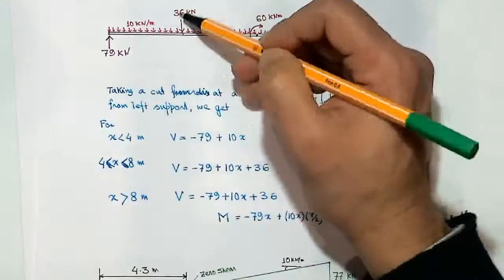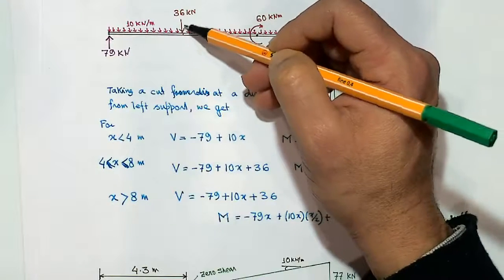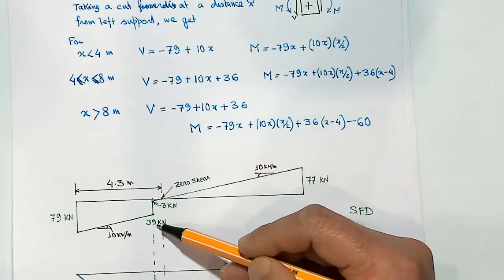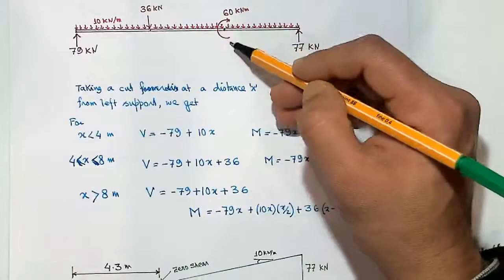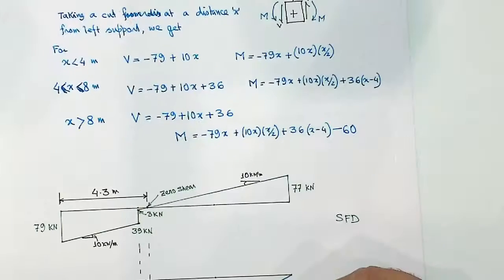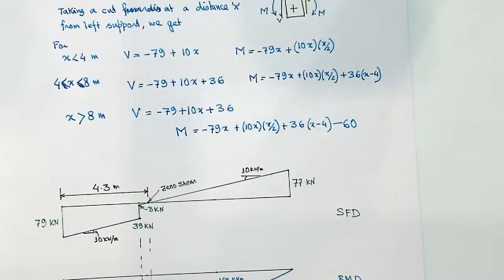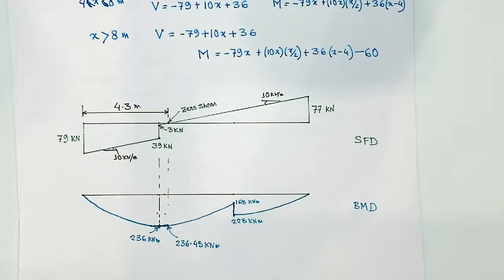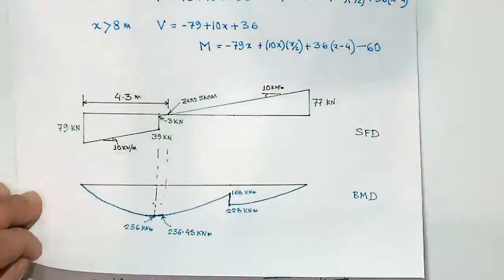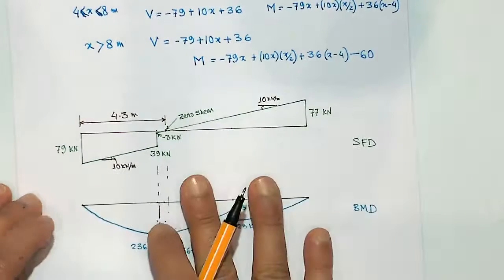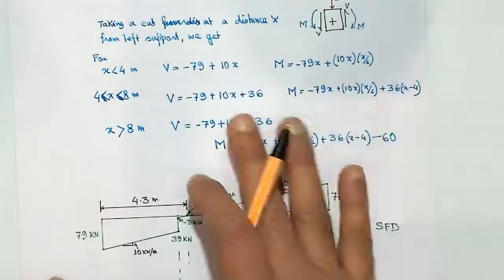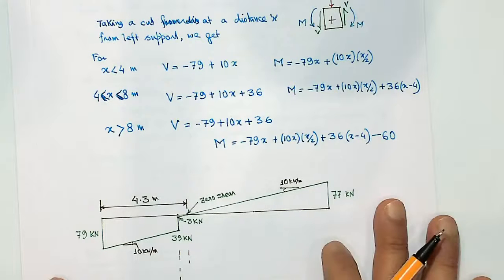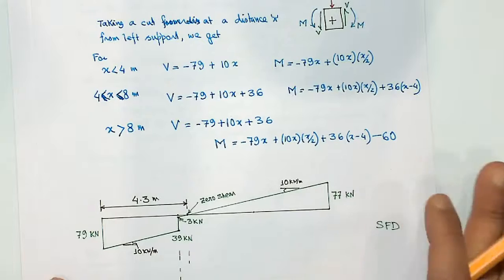Very similar to when there is a concentrated force, you get a jump in the shear force diagram. Same is true if you have got a concentrated moment, you get a jump in the bending moment diagram. So again, this is fairly straightforward from a concept point of view. This maths bit, the expressions bit, you have to work it out and do things, but other than that,